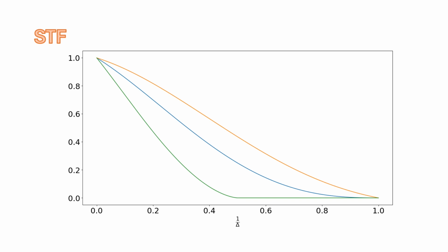The blue curve corresponds to lambda f number equal to delta, so we've undersampled relative to the optical bandpass by a factor of 2. And the bottom curve, the green curve, corresponds to delta equal to lambda f number over 2, or lambda f number equal to 2 times delta, meaning that we've sampled at exactly the Nyquist frequency for the optical response.